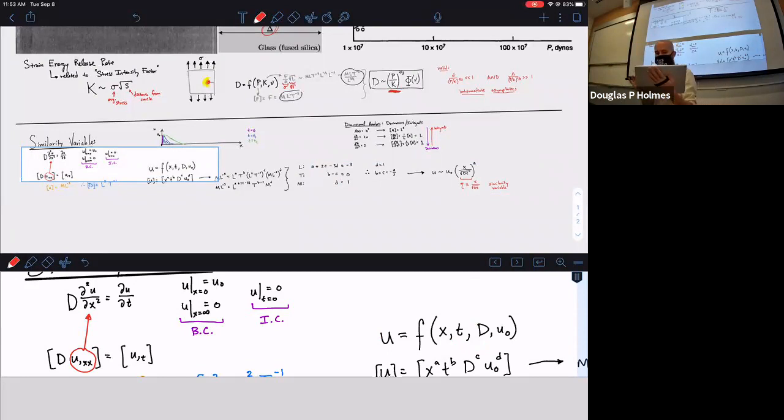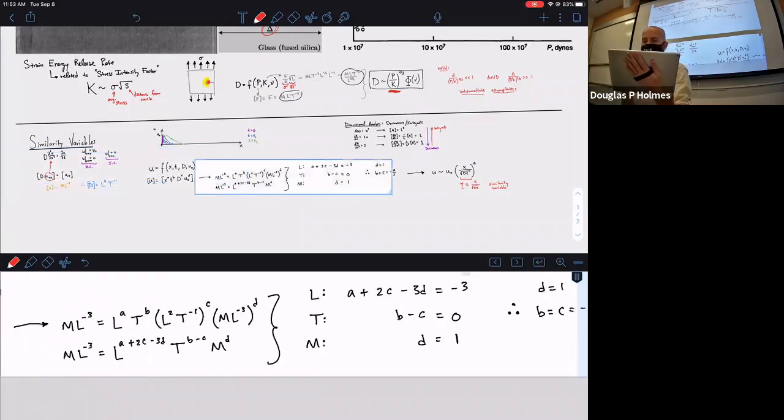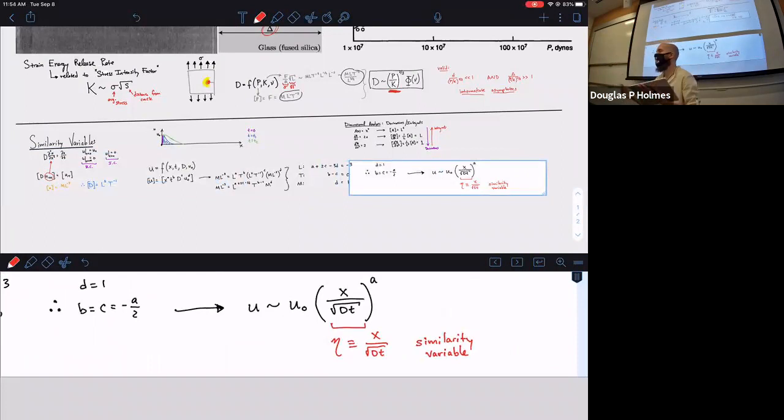So in general, if you find a dimensionless product that contains your independent variables, check to make sure that the spatial dimension is in the numerator. It'll likely make your life easier for doing a calculation. It's not required, you can do it, it's just kind of a good rule to keep in the back of your mind. Having the spatial parameter in the numerator is typically more useful when dealing with similarity parameters. When you're reading papers, you'll see this occurring as well.